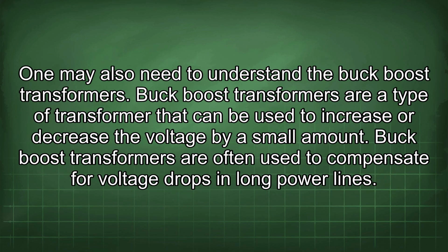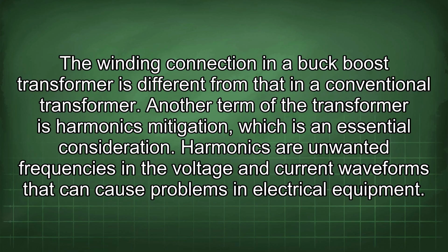One may also need to understand the buck-boost transformers. Buck-boost transformers are a type of transformer that can be used to increase or decrease the voltage by a small amount. Buck-boost transformers are often used to compensate for voltage drops in long power lines. The winding connection in a buck-boost transformer is different from that in a conventional transformer.